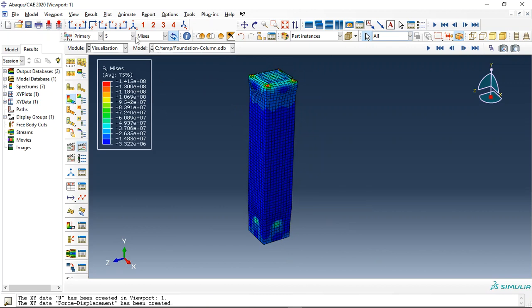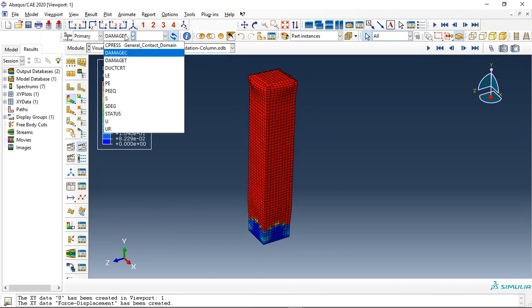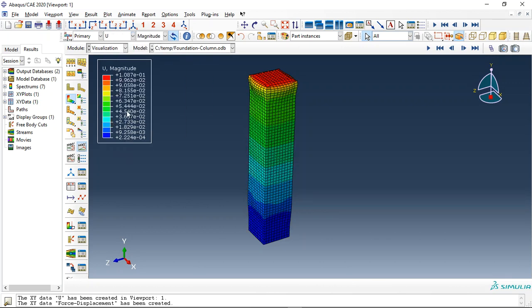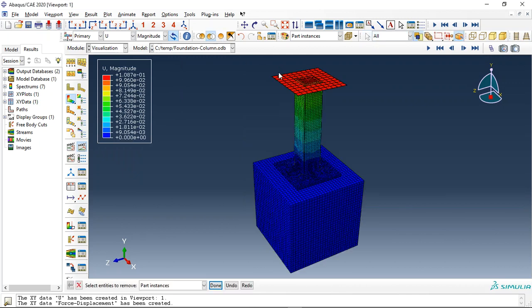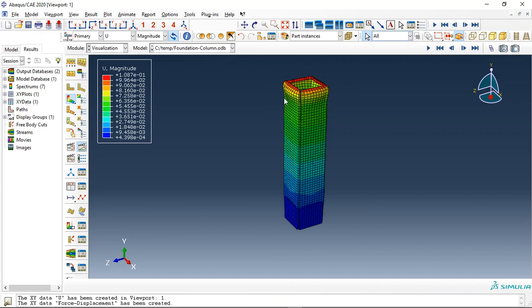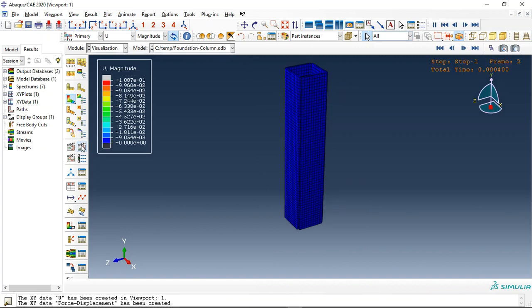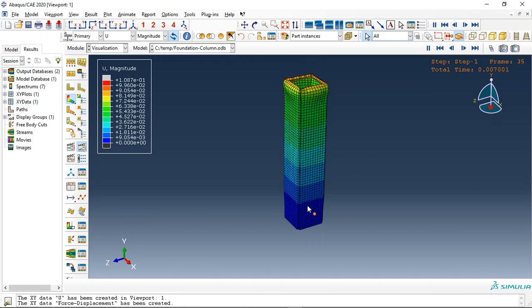Here is the stress. Then we can check the compression damage, tension damage, stiffness degradation, or displacement. Now let me replace the steel column. See the steel column, and this is the compression animation. You can see that, this is the compression test. We use reinforcement, steel angle, and stiffener at the bottom, so we have a strong zone here.